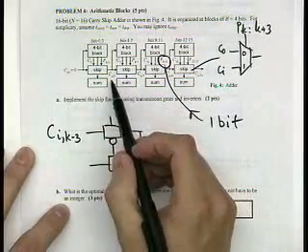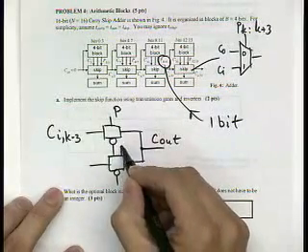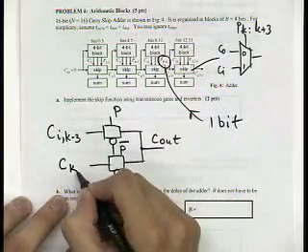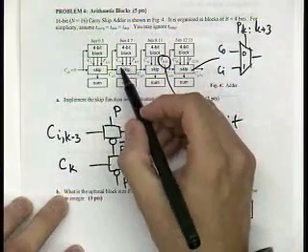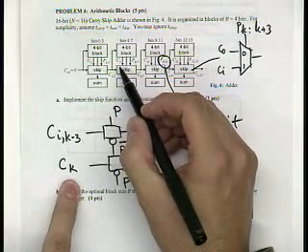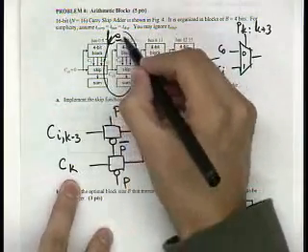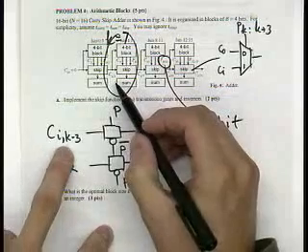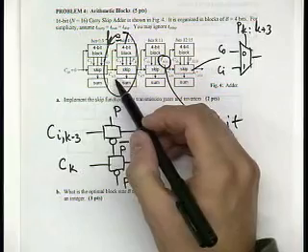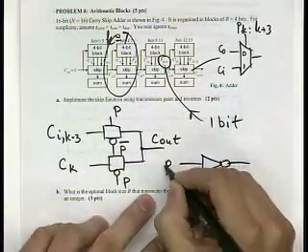So that's the incoming carry. Or if you don't have the propagate condition satisfied, this is P bar, this is also P, then you have ck, which is the carry that is generated. For example, ck here is 7, so you have k is equal to 7 for this block. You have c7, or you have incoming carry at bit position 4. So this is output carry from the previous stage, which is the incoming carry for this block. And you finally have this inverter to implement,